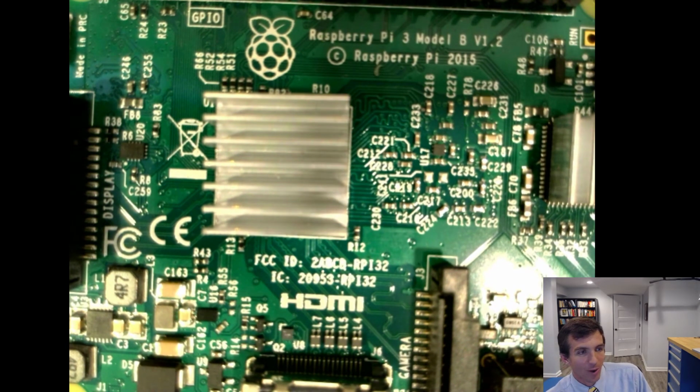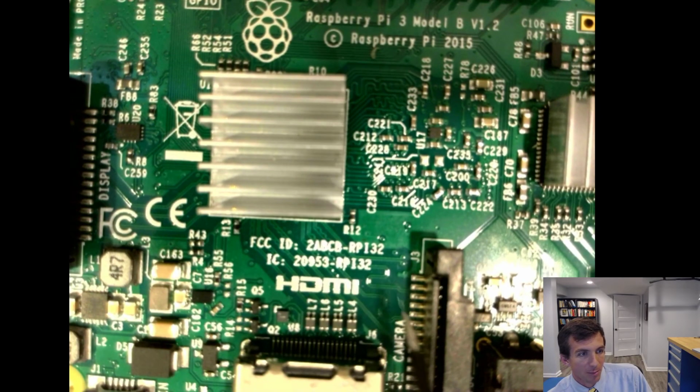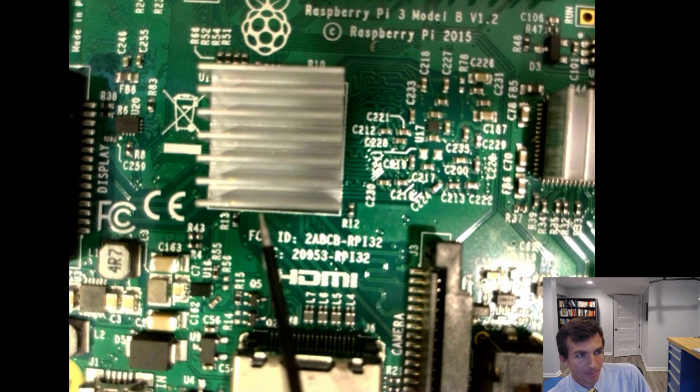We're going to be switching these wires up and down so fast that a gigahertz signal will actually propagate down this wire, and that pulse might get to the processor before this one. If I wanted to send the pattern 11001 off all these pins, I'd like for this processor to see that same pattern at the same time. So I actually have to account for the speed of these electrons flowing down here, which is super, super fast, to basically not give one leg an unfair advantage.